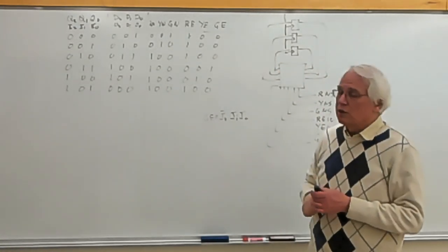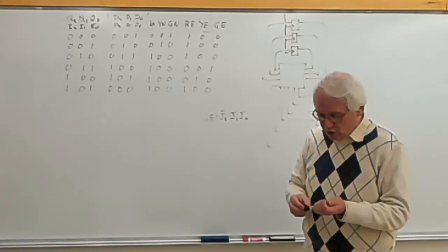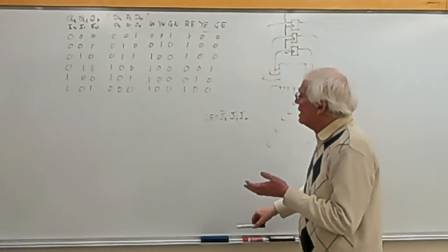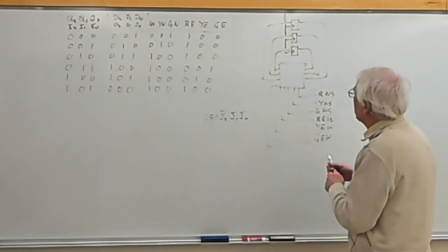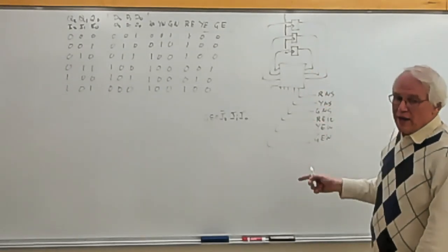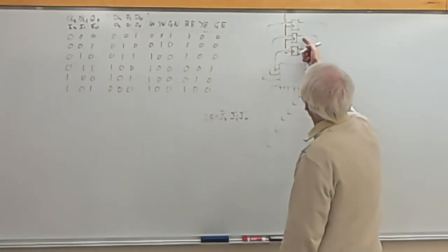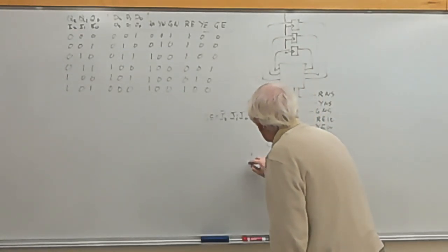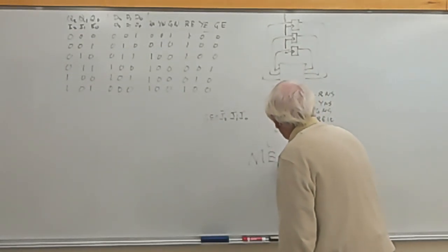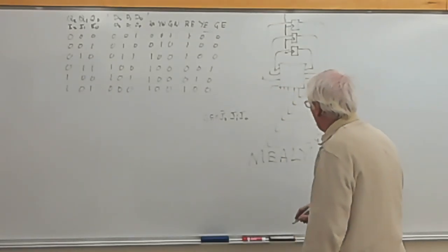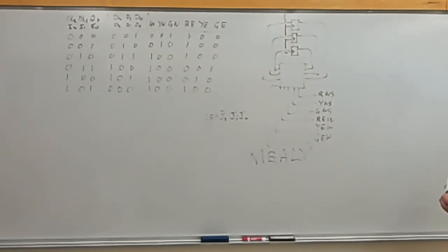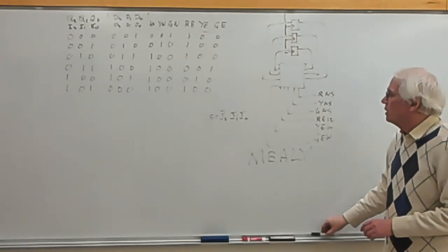I'm not going to bother to actually write out the set of equations. I just wanted you to see how we would go about designing a system like this, where the outputs come from the logic, not from the registers. And this is, unlike the Moore machine, this machine is called the Mealy arrangement for building a synchronous machine.